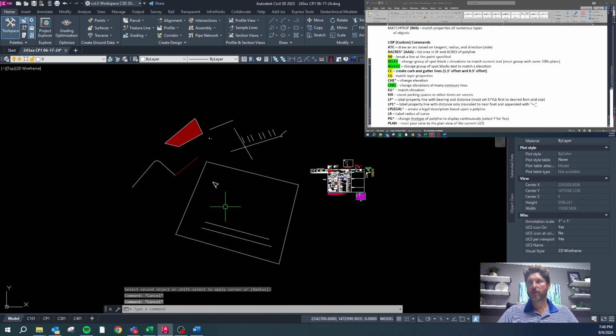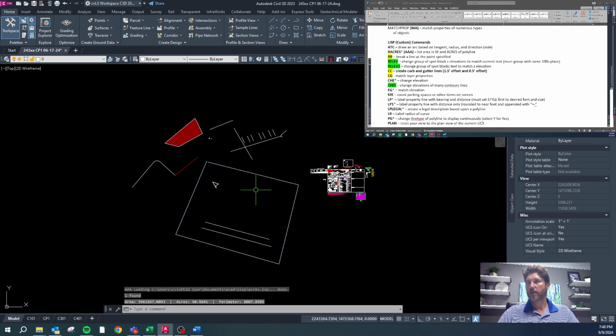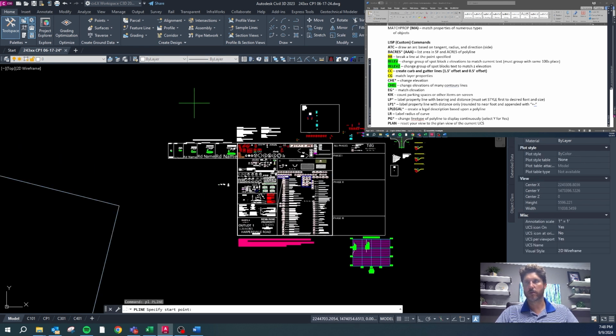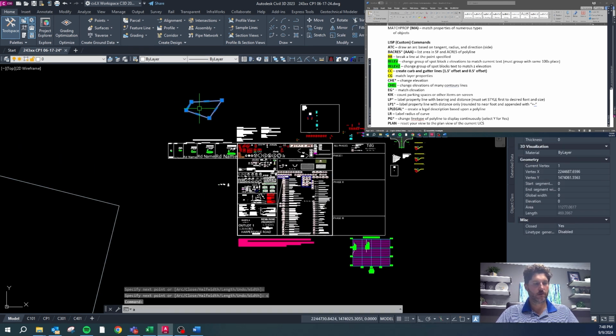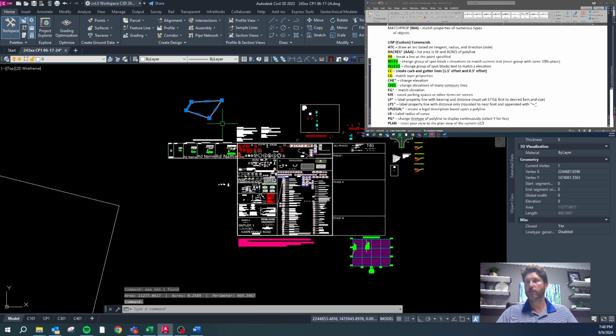All right, B acres, which we also have a quick key of AAA, and so I can click that. This thing is a ton of acres. Let me draw something that's a little bit smaller. So you can hit C to close. AAA. So that is a 1/4 acre, and it's 11,000 square feet, and the perimeter is 470 feet roughly, or units. Our units are always feet.